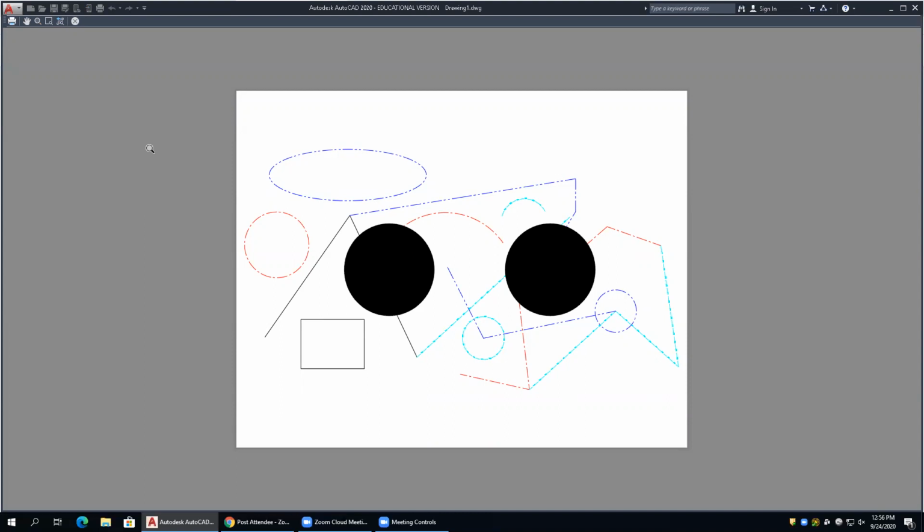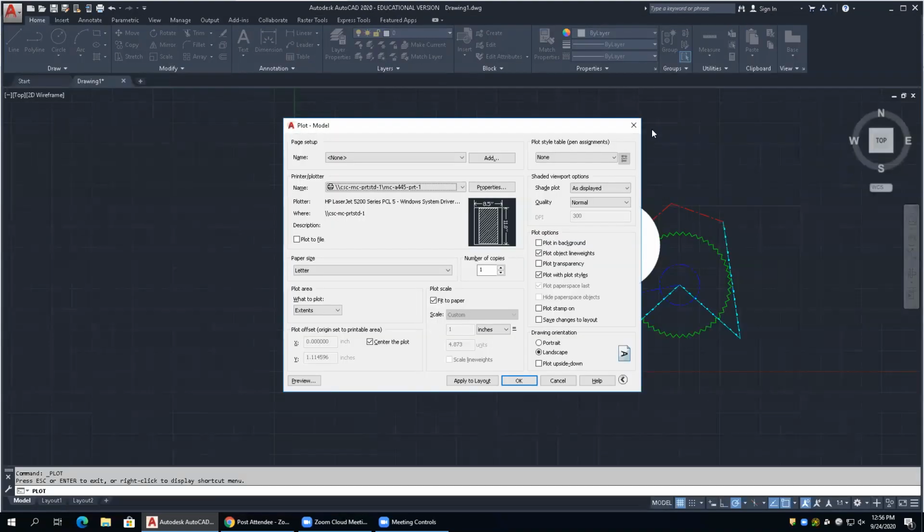Preview. Well, we're going to go look at your layers, and guess what? Everything's set, no plot, no plot, no plot. That happens, okay? It can happen real easily. So you have to be careful when you're using no plot options. Okay? Is everybody okay with that?